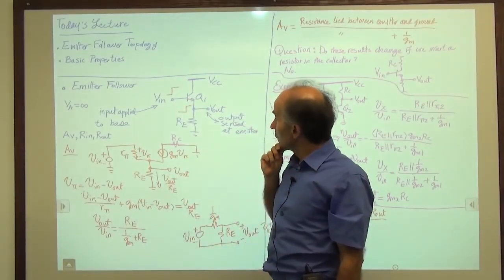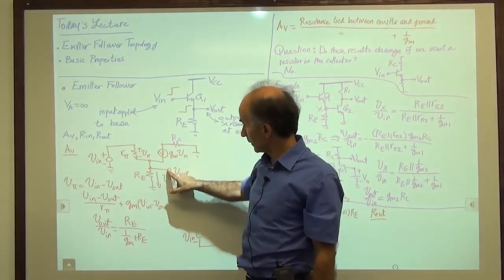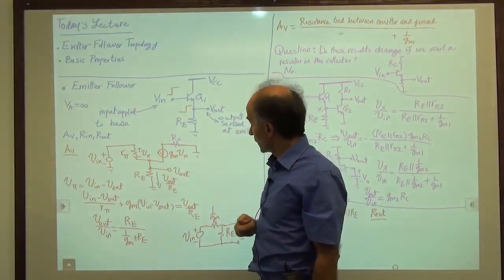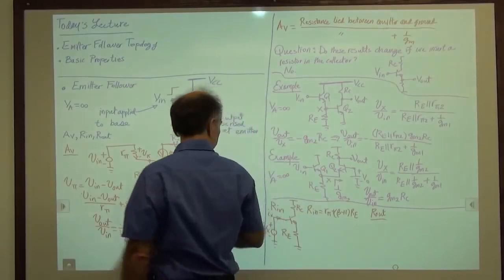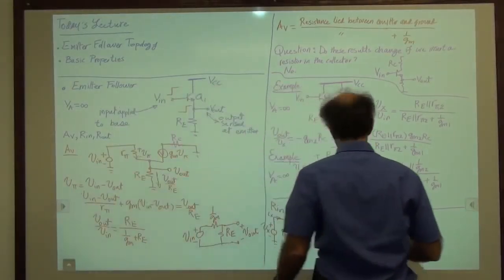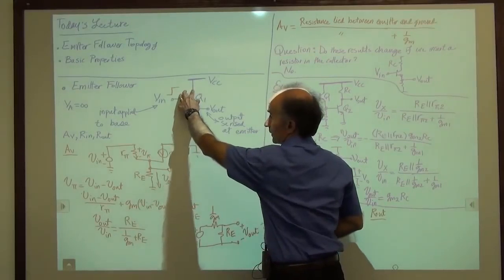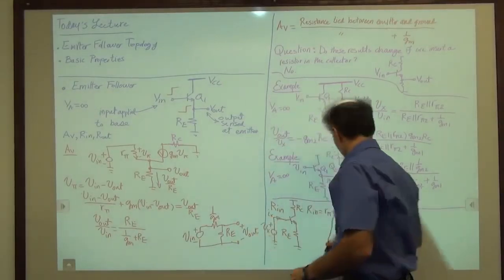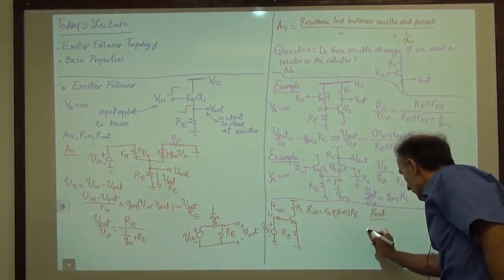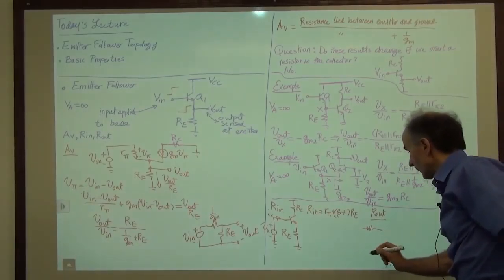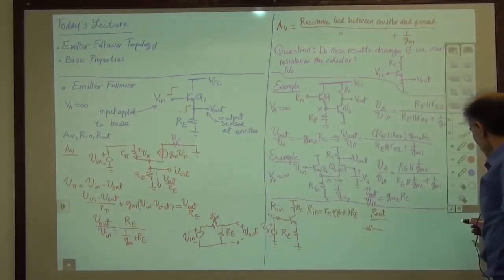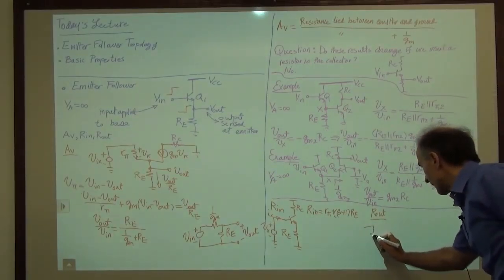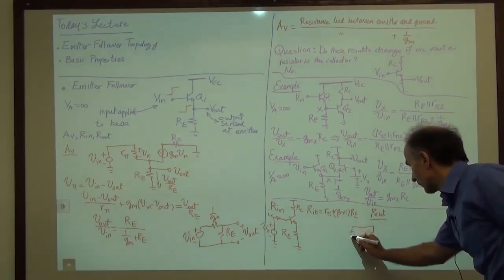This is similar to finding the Thevenin equivalent of the circuit. Okay, so certainly we can do that, not a big deal. I can sit here and do that calculation, right? I can set this to 0 and so forth. So let's do that, but with a slight modification. I will draw the small signal model of the transistor knowing that Vin has to be 0 for output resistance calculation. So let's do that. Here's our, sorry, let me do this. All right, so we set our input to 0.